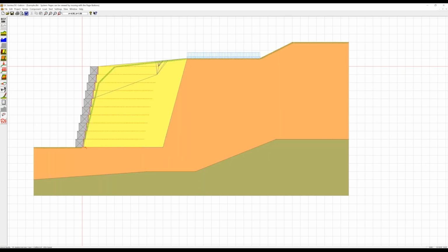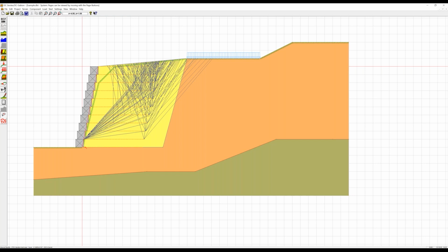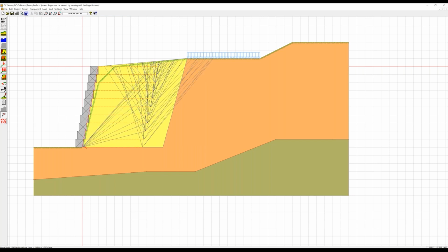And you see that all these different soil blocks are calculated for the internal stability. We are looking for the block with the least safety, the critical safety for this construction. And these geosynthetics layers may as well be lengthened if they are not sufficient. And up to this time now, it's still a sufficient length. They are not lengthened yet. So this is quite a complex calculation, which does a large iteration for all the possible blocks, which might be the critical failure plane.